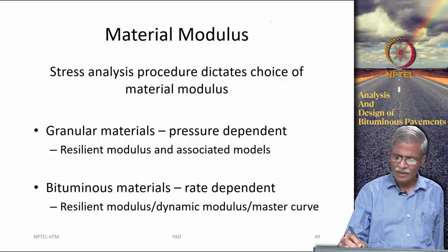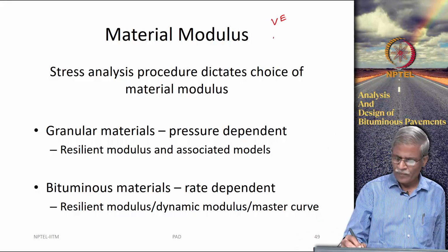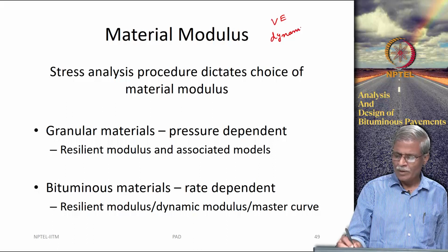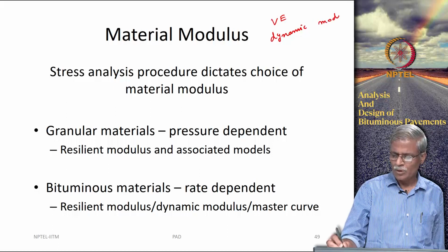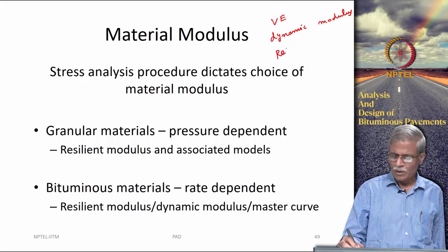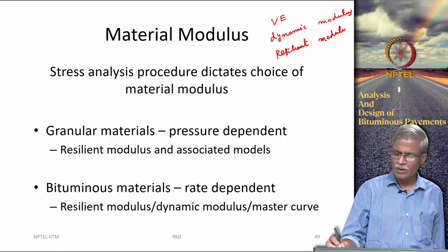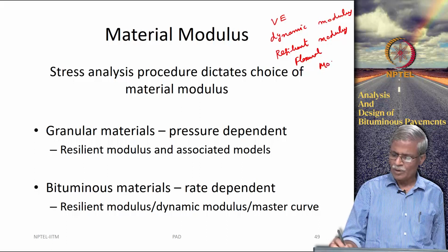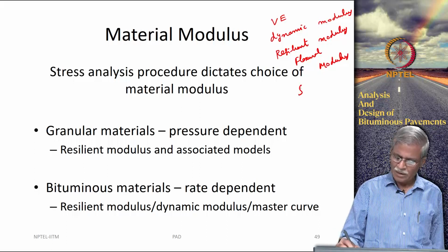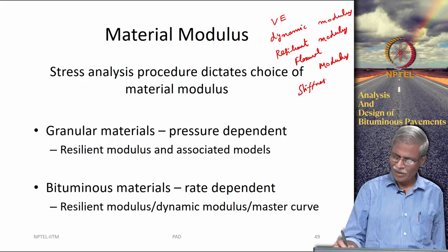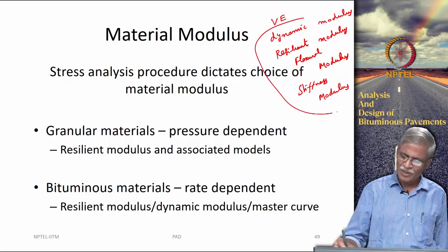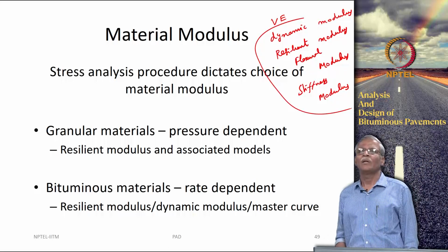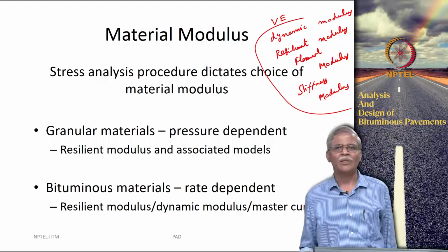So, let me just write it: viscoelasticity, dynamic modulus, resilient modulus, flexural modulus, and I can keep adding more to it, stiffness modulus. So, these are various ways in which the time dependent nature of the bituminous material is actually measured.